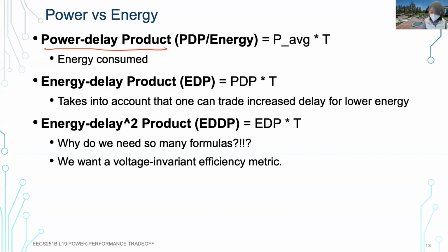Another one you will hear more often, and we'll talk a lot about, is energy delay product, because it shows the trade-off between the total energy being consumed and the performance we benefit from that energy. This especially matters when we come to the trade-off of whether we want to emphasize energy consumption or we really care about performance. This is a trade-off we see a lot in hardware design, trying to balance the energy and the delay product. So that's the middle one.